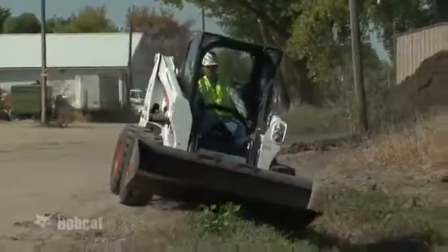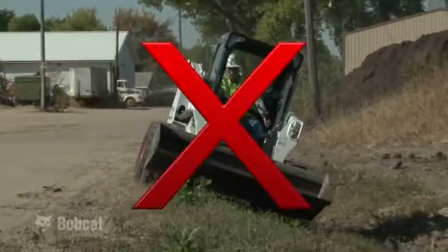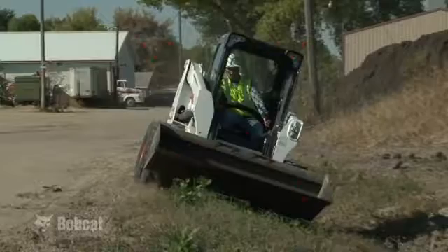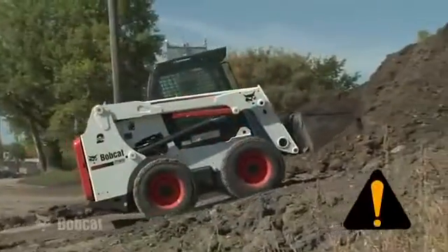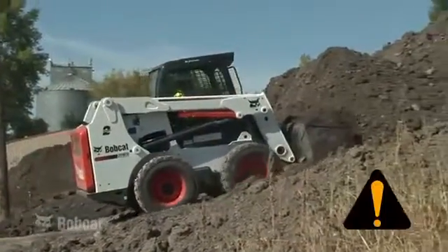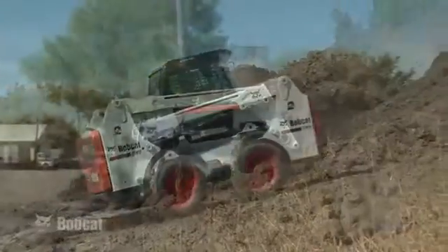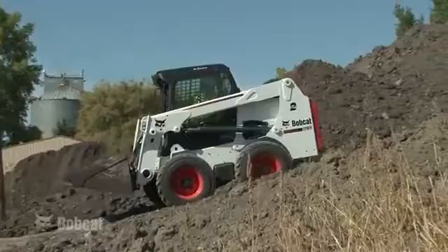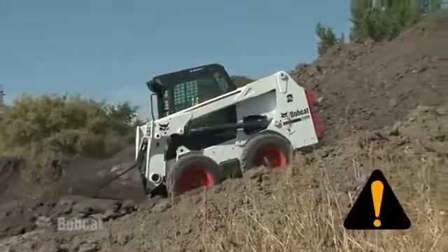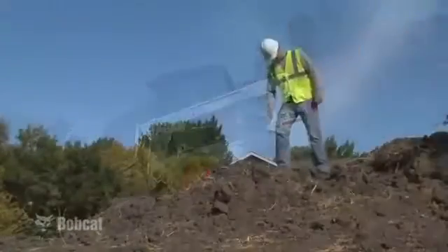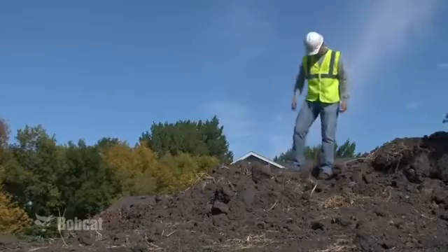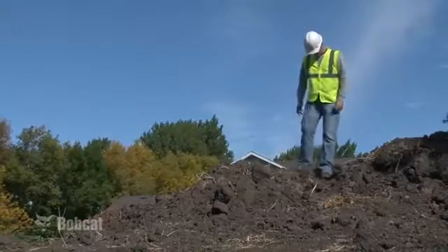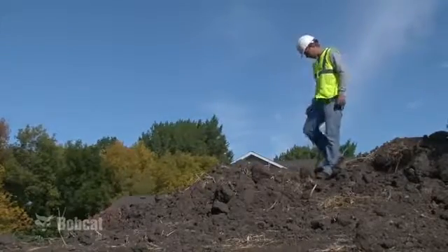Be careful on slopes and avoid traveling across steep slopes. Drive straight up or down slopes and keep the heavy end of the loader uphill. With no load, the rear is heavier. Refer to the operation and maintenance manual for specific instructions for your loader. Always check the surface conditions for adequate traction to avoid sliding down a slippery slope, causing a rollover.